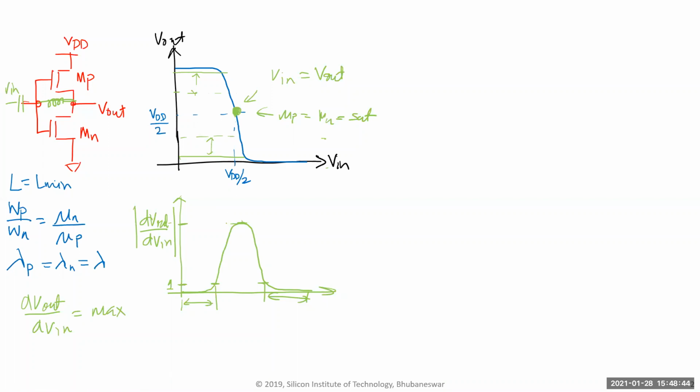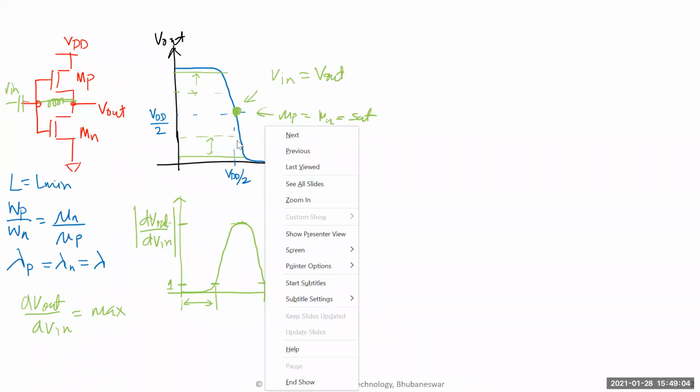But in IC design, we can get good capacitors. Even a small capacitor is okay, because we're operating this at high frequencies, but a very high value inductor is impossible to get. Basically, one inductor will be the size of a chip, and that's what people use. You'll see half of the chip is an inductor for RF amplifiers. But in this case, we can't use it. So in IC design, typically we don't put an inductor.